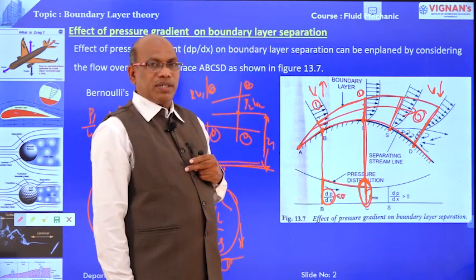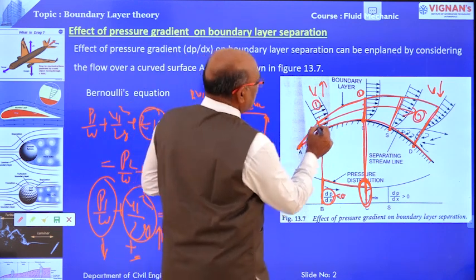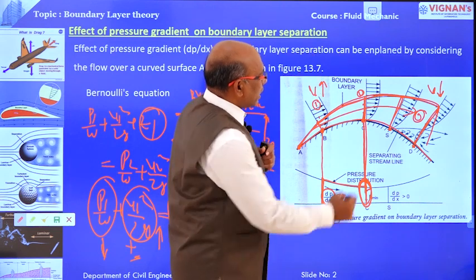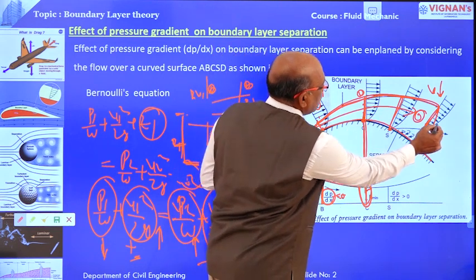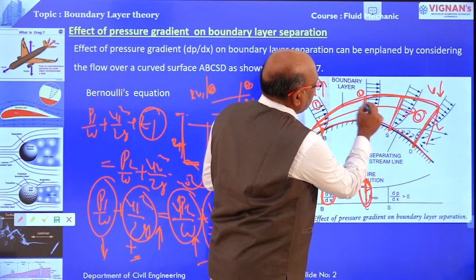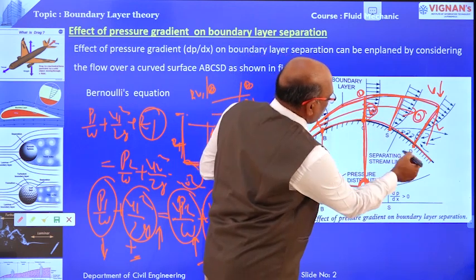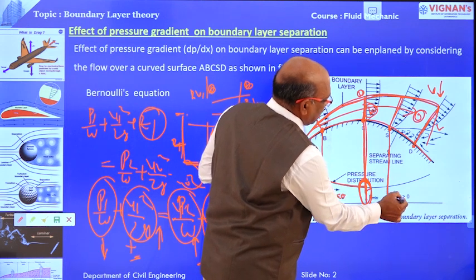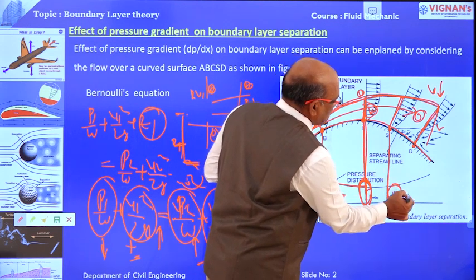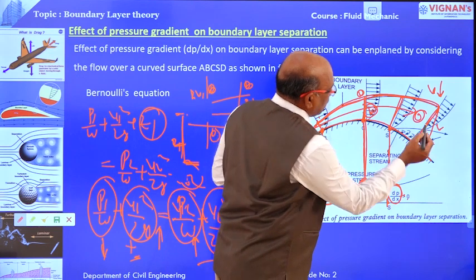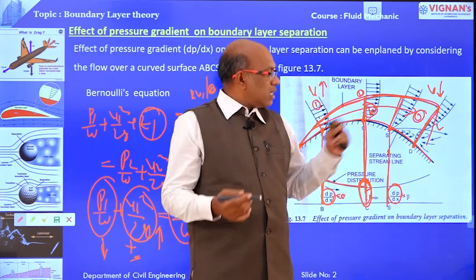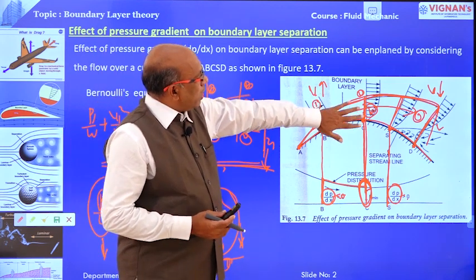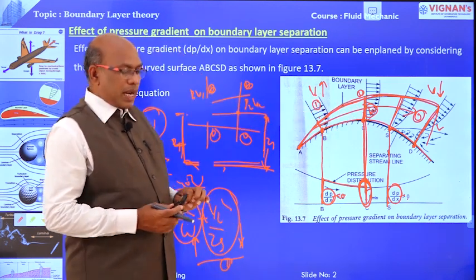this point. And again the boundary layer cross-sectional area gradually increases, and the velocity also reduces here compared with this point. Velocity reduces automatically, so the pressure gradient increases, therefore ∂P/∂x is more than 0. Beyond this point again pressure increases and velocity decreases. This is the phenomenon related to boundary layer theory, right?